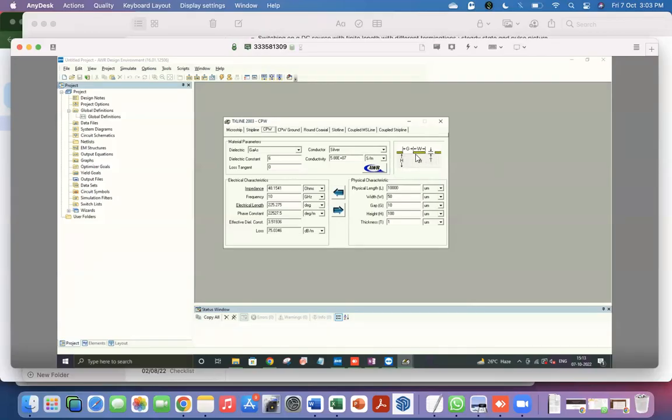Because both you can change, and both of them are, on the surface. So what I mean is that you could start with something which looks like this, and then you can narrow this to something very small. And in order to maintain 50 ohms, you reduce the gap between the two as well, and you bring it close. I mean, this is a horrible drawing, but you know what I mean.